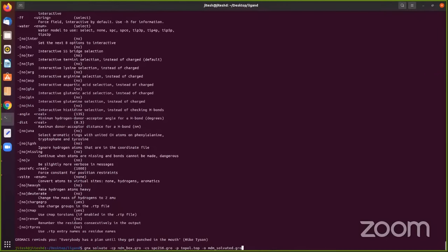Mixed solvent models can also be done in a similar way. Just like for every type of solvent, just specify this and randomly it will be filled. But for mixed solvent, it is recommended that you first use PackMol or other types of software to pack the entire unit cell that you are forming with the mixed solvents the way you want, the distribution, the density, and then use it. Do not use this directly for solvation.